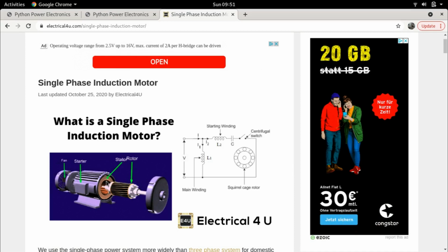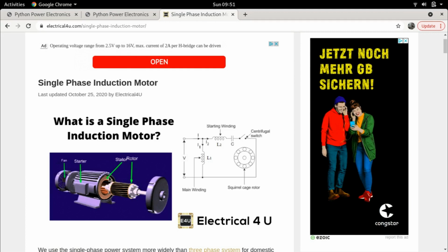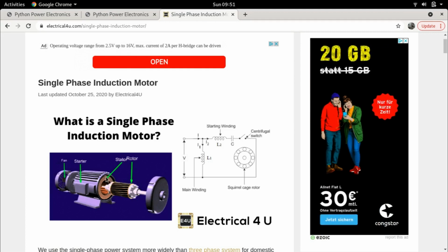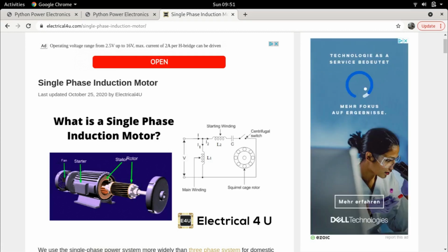On the contrary, the permeability of iron or many other metals, because nowadays we don't just use iron, we use alloys, is extremely high, sometimes 1000 times higher than that of air. Therefore, the flux flowing through the metallic part will have a much lower reluctance, almost 1000 times smaller than that of air, which means the flux is going to be much stronger.